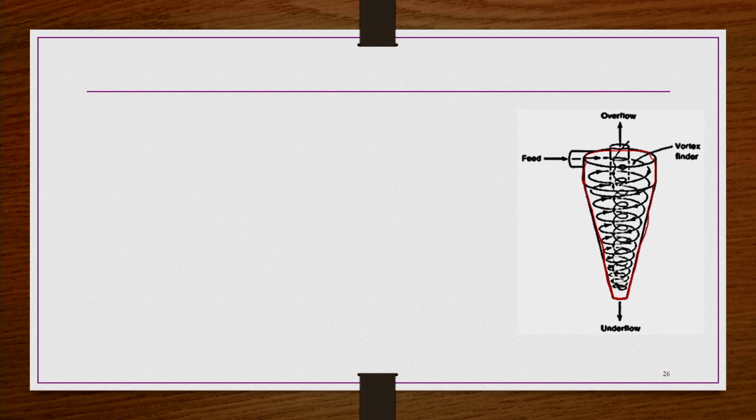Okay. So, now the feed comes in here at high velocity like this, and then this hits the wall, and because of that it undergoes a kind of rotational motion like this, and because of this rotational motion, a centrifugal field will be developed. So, this feed containing the particles will be going through a kind of rotational motion like this, okay.